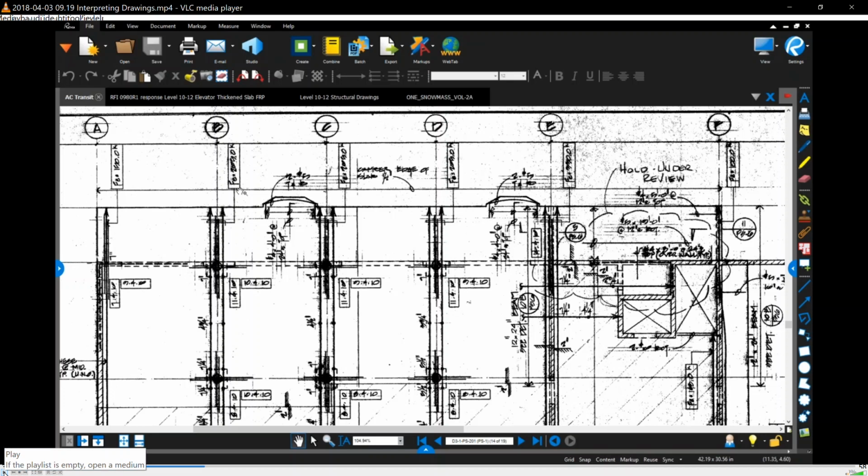You got it? Any questions? No? Okay. So typically, at least at Watchery, we design cables to be an effective pre-stress force of 26.8 kips per cable. So you basically do the math. I'm not sure when these drawings were created if that's what they used, but when I was there, that's what they used.